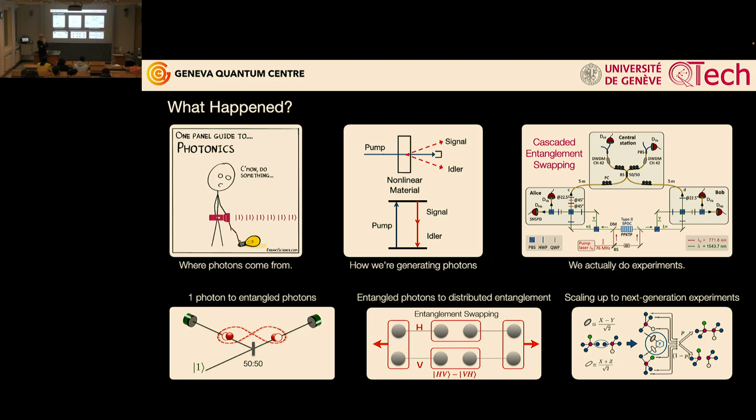Generally temperature. I don't have a plot here, but depending on the length of the fiber, you can have a meter in length change. You'll see this for buried cables under the ground. There's a sort of inertia. They don't move so much, but you'll see the length changing between daytime and nighttime. And if you've got aerial fibers and you're doing something in polarization, you can really see the polarization swinging in the breeze.